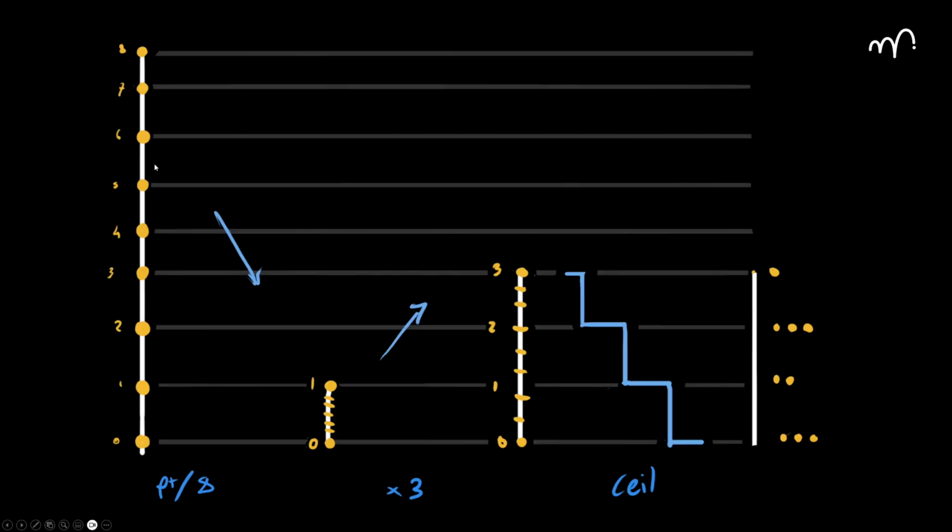So this is what we're going to be doing. We're going to be getting the line itself, which will contain X amount of points and primitives. In this case, we're going to do it on primitives. But let's say our primitives go from 0 to 8 on our line that has X amount of distance. If we divide each primitive number by the max primitive number itself, which in this case is 9, it's not 8, since we also have an index 0, so 1, 2, 3, 4, 5, 6, 7, 8, 9. If we divide each number by the maximum, we get a normalized length basically, we're going to resample or rescale or give an attribute to each primitive that goes from 0 to 1.